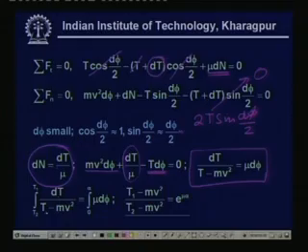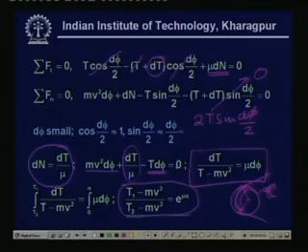So, that comes out to be dt by t minus m v square, and you have seen in this particular pulley what we have drawn earlier. So, this comes out to be your angle of wrap, that is alpha we are considering. So, we consider from 0 to alpha the entire length from where T2 to T1 has occurred. So, this is 0 to alpha mu d phi. So, preliminary integration gives us that T1 minus m v square equals e to the power mu alpha.